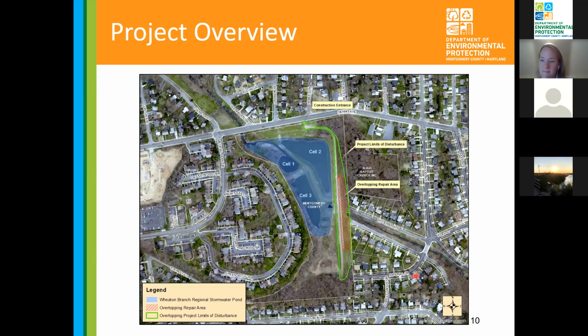Well, I guess one of you said that overtopping seems to be the biggest cause of failure. So if this is the most important part of the dam, that you want the best structure to keep the dam from breaching or whatever, then is overtopping what you want to use? You're exactly right. And part of this assignment, the part of this work by designers, was to evaluate different alternatives for overtopping protection.